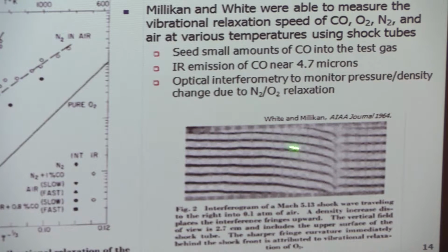These are called fringes. So this was a measurement. This is an interferometry-based scheme. You measure this fringe shift and the characteristic time over which it evolves, and you can infer tau. So that's a density-based optical system for measuring these characteristic times and seeing what they are.